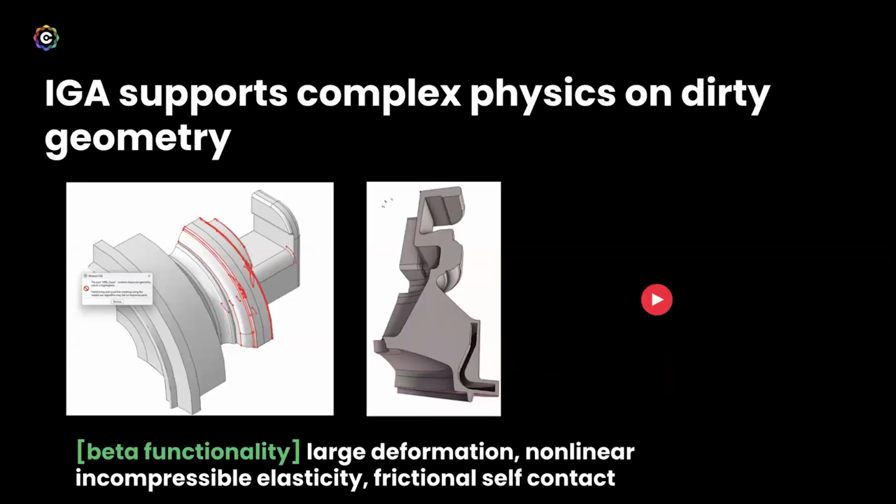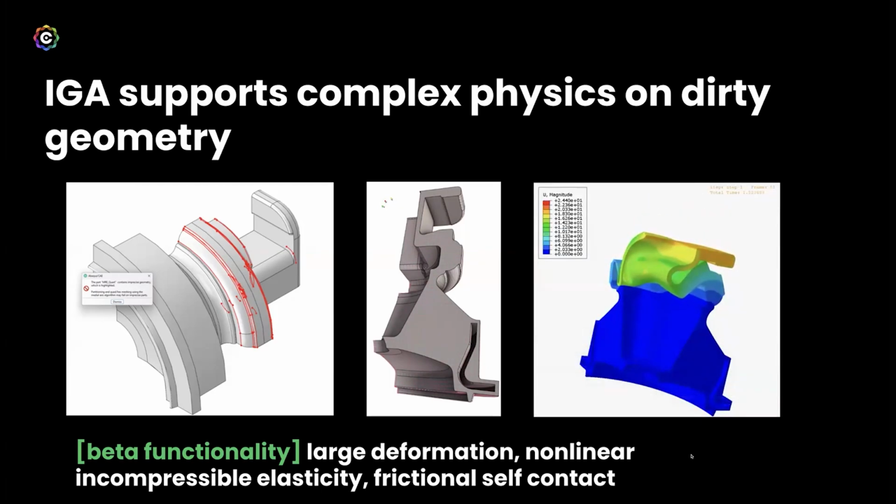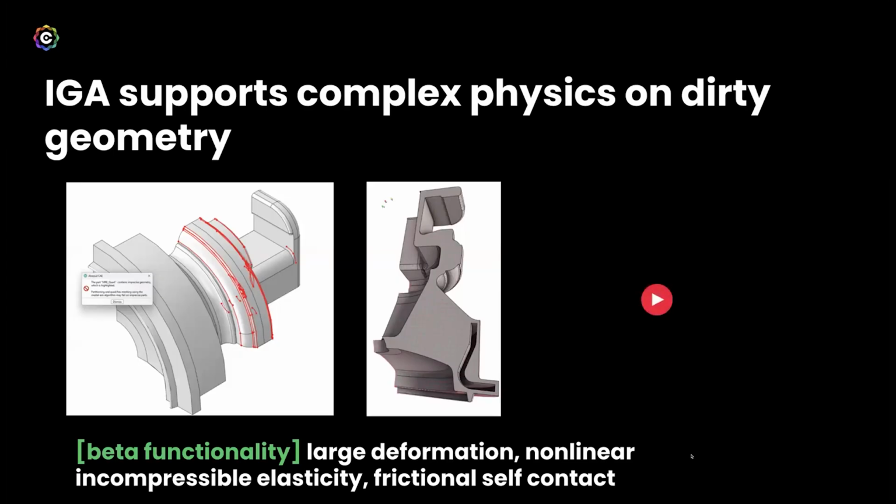That can cause a lot of issues if you're trying to build a hex mesh as you're doing partitioning. If your partitions start to interfere with some of those imprecise entities, it can cause issues that make it unable to proceed forward without healing or additional cleanup. And this model, as you can see in the middle example here, is able to trim mesh just fine with no issues.